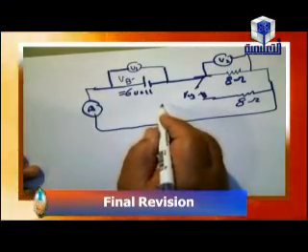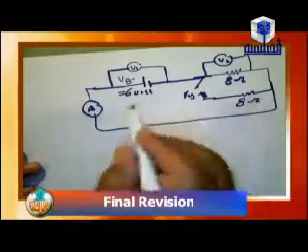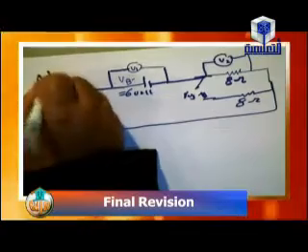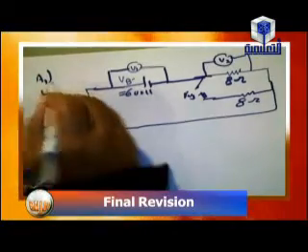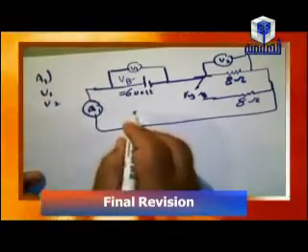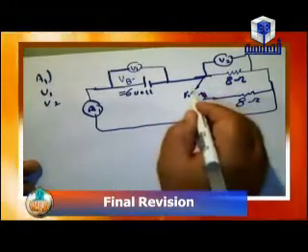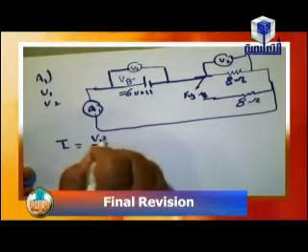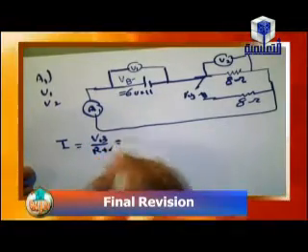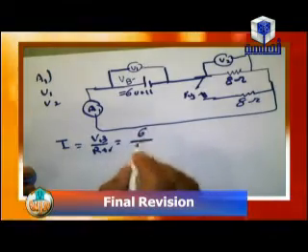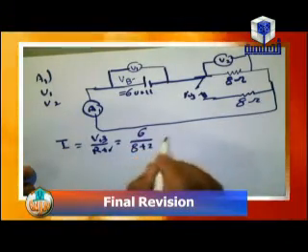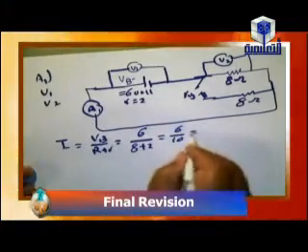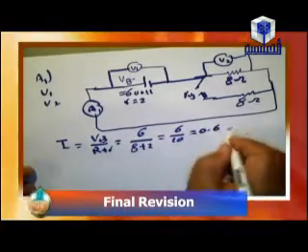For the circuit shown in the figure, find the reading of ammeter A1, and V1 and V2. We find first when the key is open and when the key is closed. I equals VB over R plus r, equals 6 over 8 plus 2, where the internal resistance equals 2, which is 6 over 10, equal to 0.6 ampere.